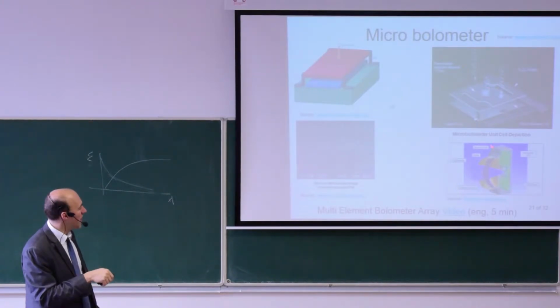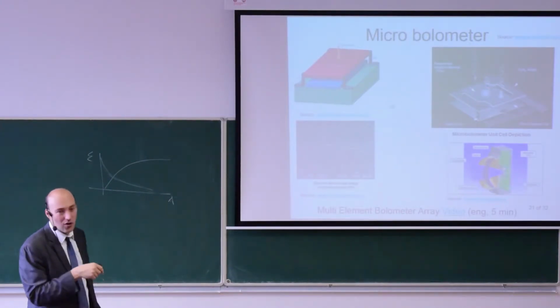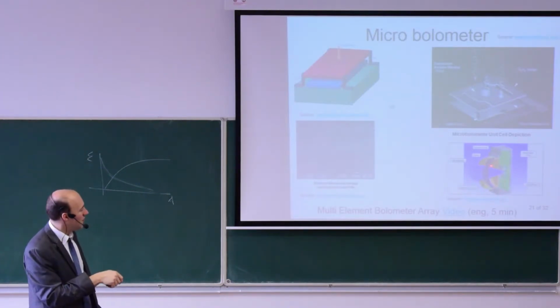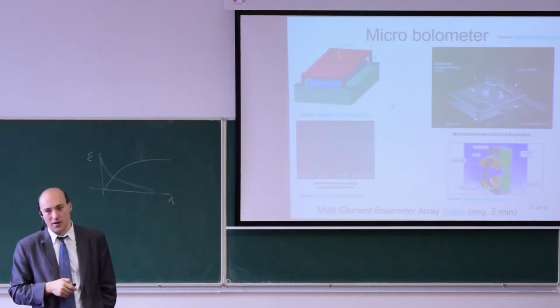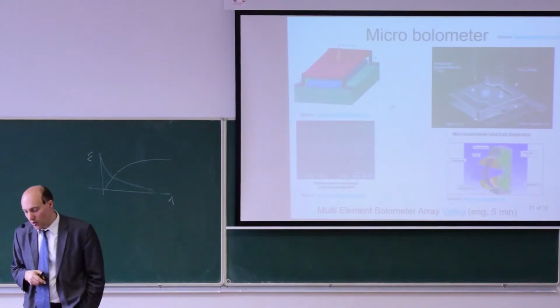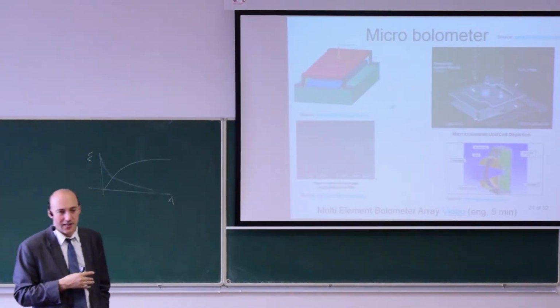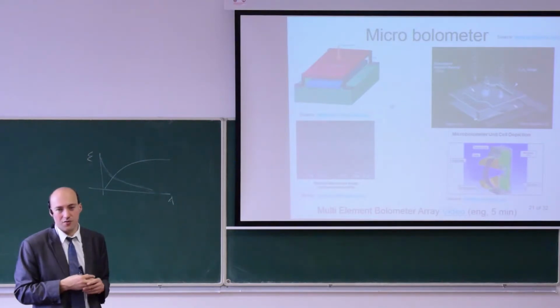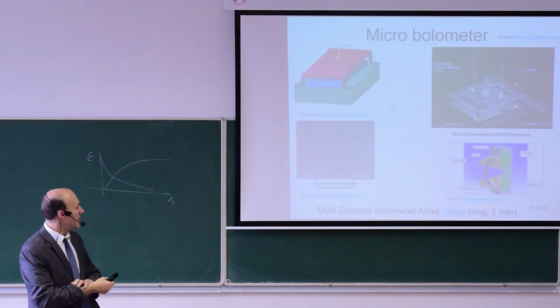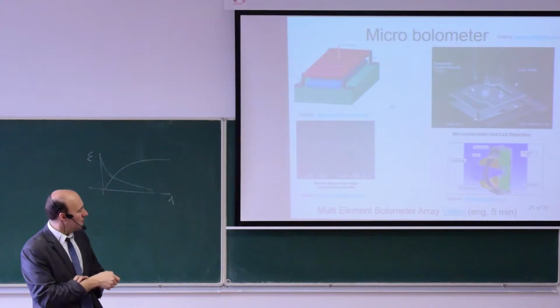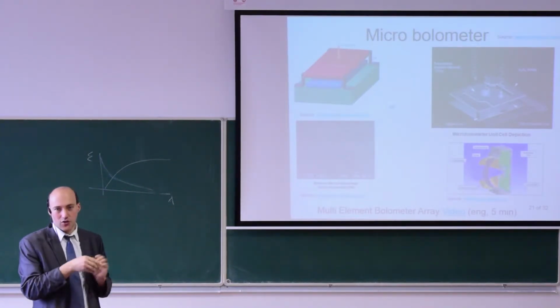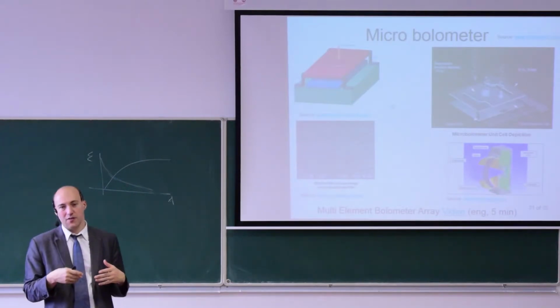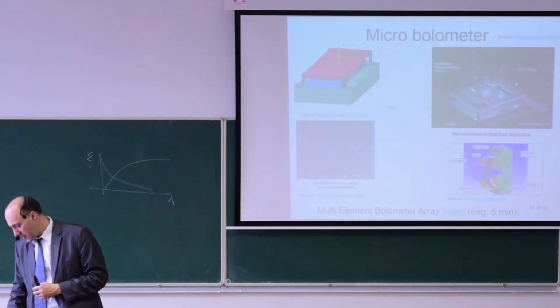So the single chip is then placed at the focal point of a lens. Here we have a lens that will focus the infrared radiation. We already know that the lens needs to be from a different material than glass, such as silicon or germanium, for example. And we read out the different temperatures from different pixels, and this will give us the thermal image.